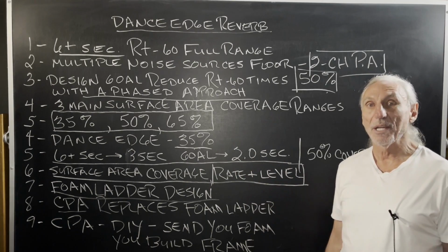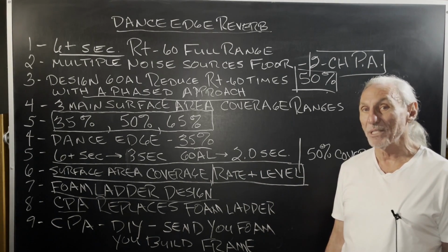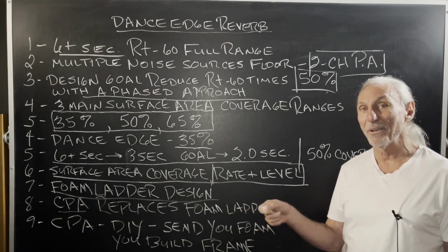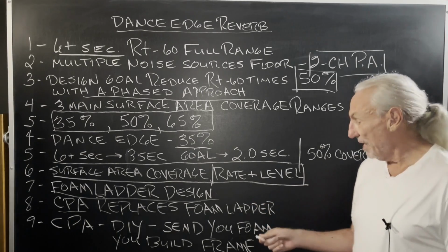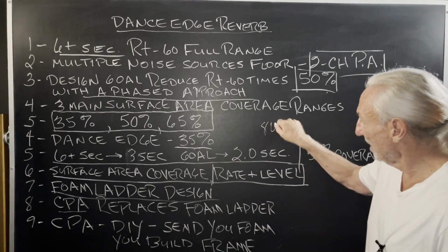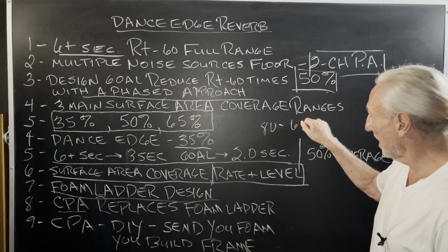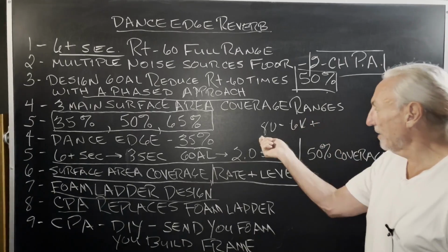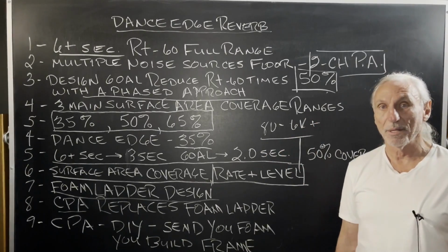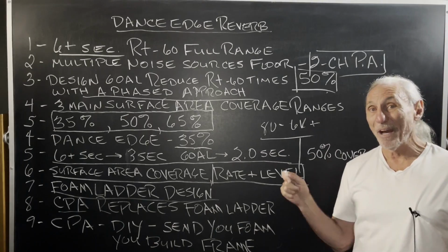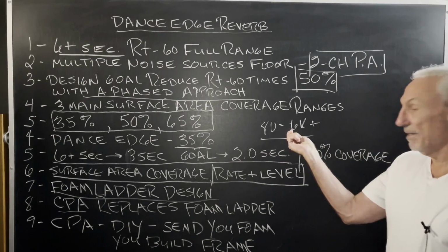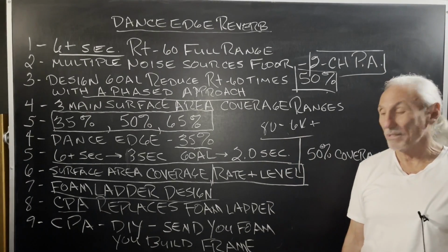And there's calculations to determine the resonant frequency of that. So it gets down into the 80 cycle range. So now we've got a product that's 80 to 6K plus. And that's a good range for reverb management. 125 to 500 is ideal. Well, we get that in spades.